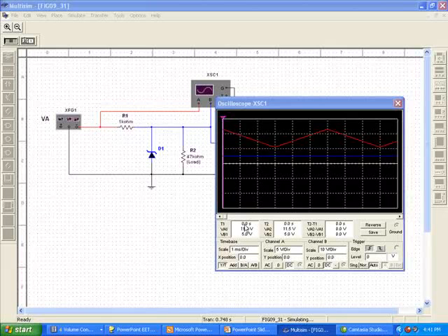This is showing that in relation to time, this started at 0, and so if we grab 2 and bring it over to here, and bring this one over here. And so what you'll see here is that the time between T1 and T2 is 3 milliseconds. The voltage at T2 is 5.6 volts, and the blue is 5.